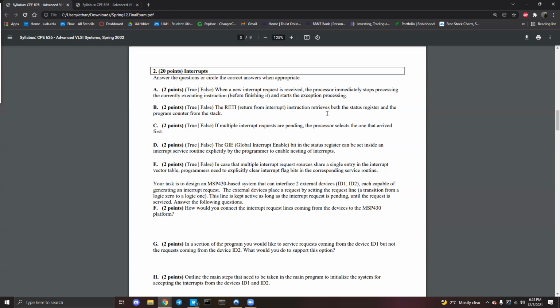However it was sent, it needs to be returned in the reverse order, because of how maybe the stack works. Maybe because if you send the next instruction's address, okay, so PC, you'll want your current one to finish, and it may update the status register in between that process. Who knows? So you may want the status register absolutely last to make sure there's no errors. But there's probably a good reason for it.